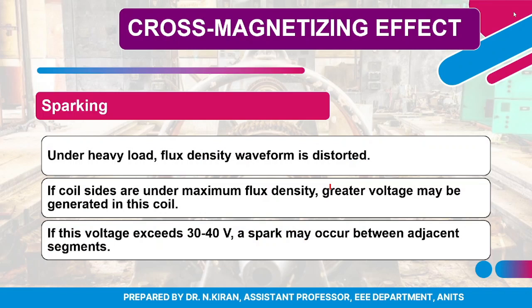Due to this poor commutation, the MNA axis has been shifted, as you have seen in armature reaction. After it gets shifted, the brush should always be along the MNA axis. Previously, when GNA and MNA were coinciding with one another, the brush was along the GNA and MNA.